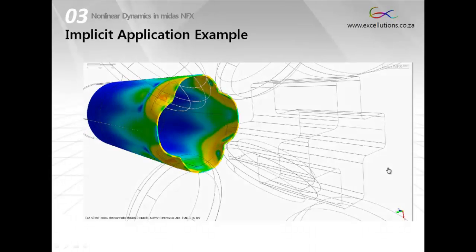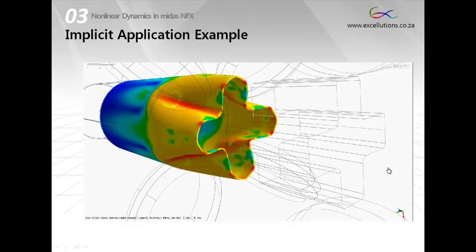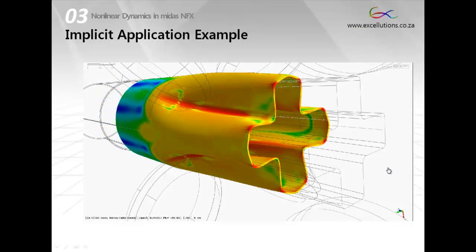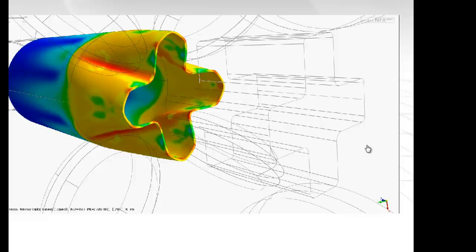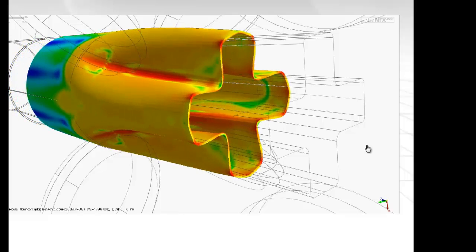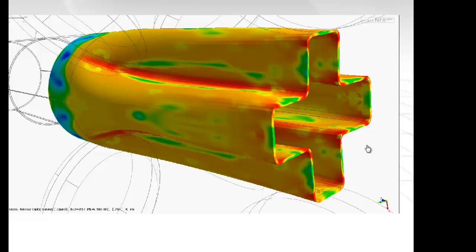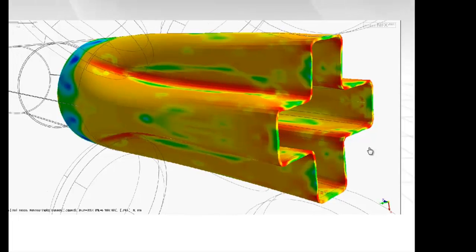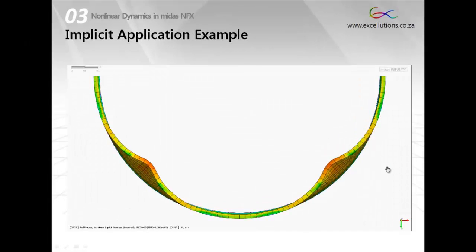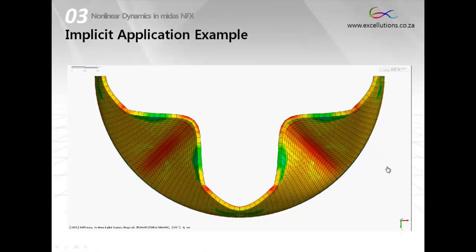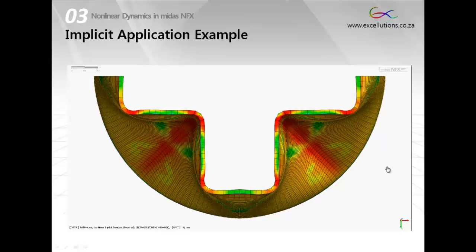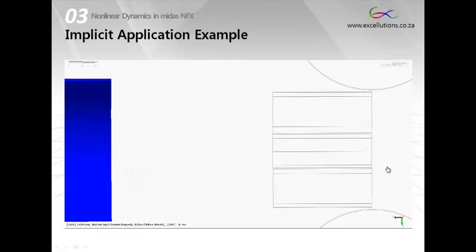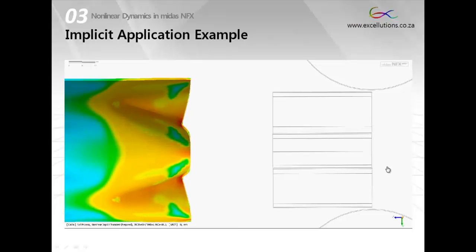This final animation in the implicit FEA example shows the rollers as rigid surfaces and a section moving through them, inducing the deformed shape that we require. These forces were extracted and applied to the actual machine to make sure that we have sufficient stiffness in our structure to obtain the rolling tolerances.